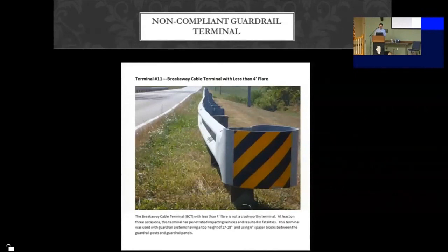The way that we were able to do that, again using GIS, goes back to how I started this presentation, and that's with our inventory. Our inventory contains the speed limit attribute. It contains our functional classification of the roadways. So when you overlay your guardrail inventory layer with your highway layer that contains those attributes, you can do a very easy spatial analysis. And that's what we did. Within 10 minutes or some ridiculous amount of time, we were able to identify the first 200 that we were going to do.